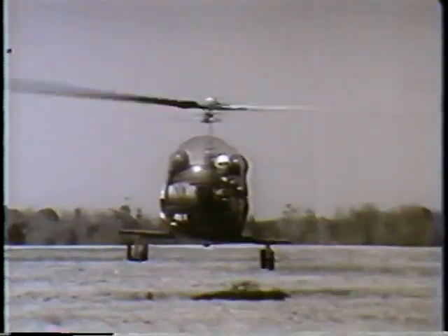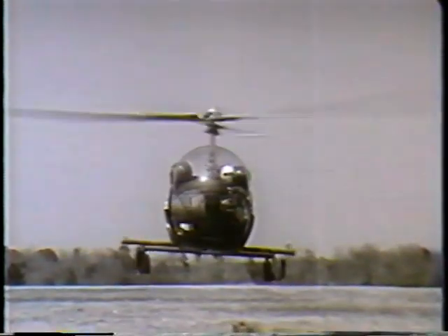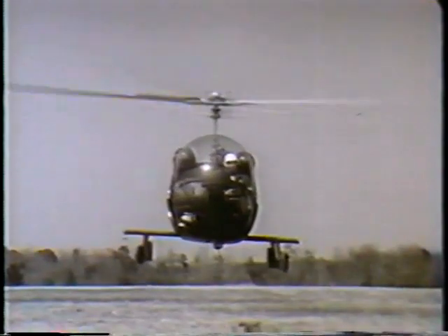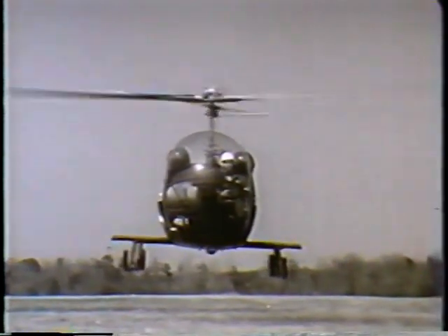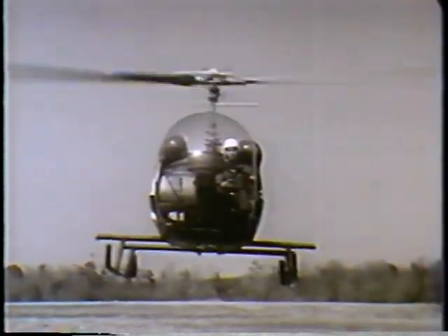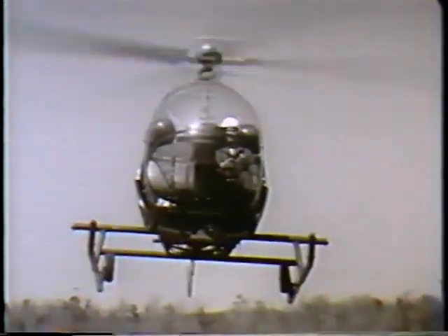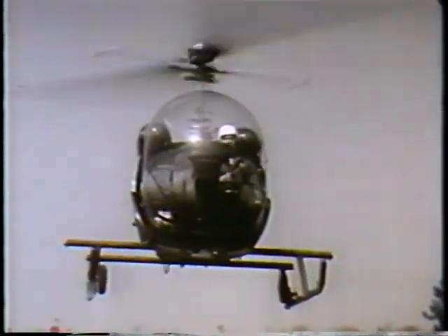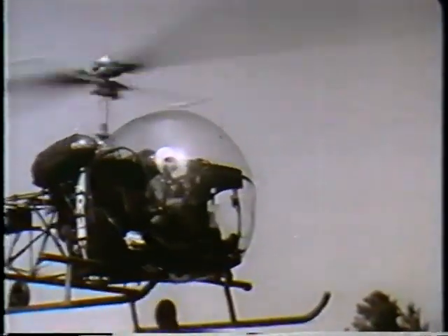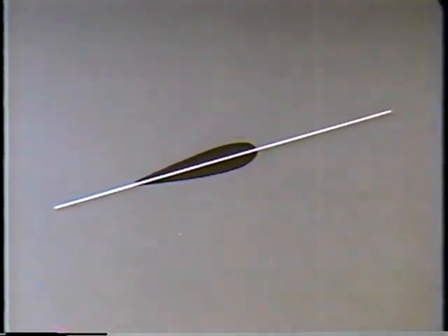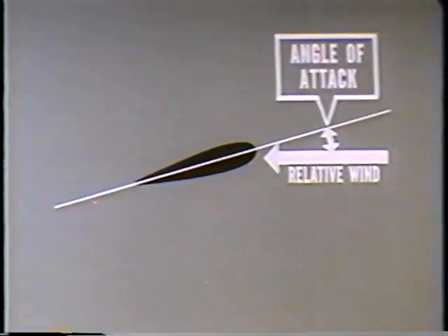A variable angle of incidence has a single but extremely important function. It enables the pilot to control his angle of attack, and angle of attack is one of the most important determining factors in producing lift. Angle of attack is the angle between the chord line of the airfoil and the relative wind.